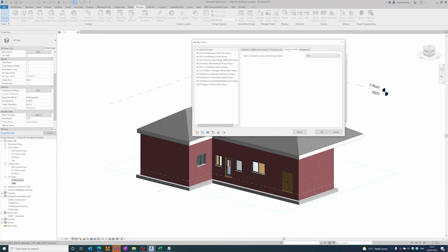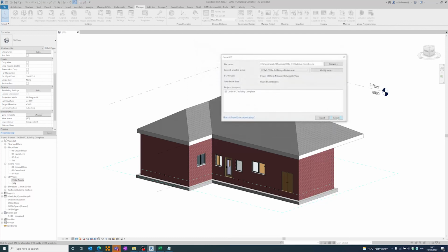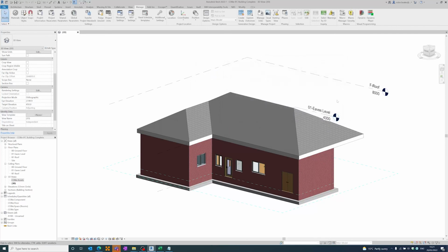We have other options should you need to use them. One particular one that is of use is the ability to store the global unique identifier against each individual object when you export the IFC. This entire toolset is very well documented online. Following that process, you can correctly export an IFC using Autodesk Revit.